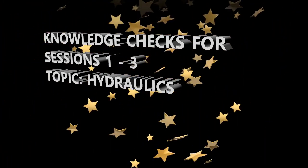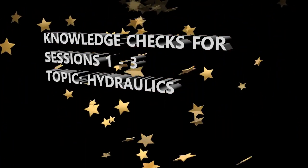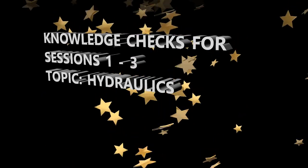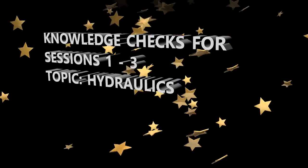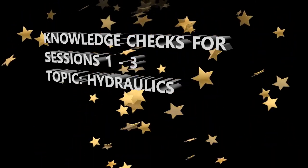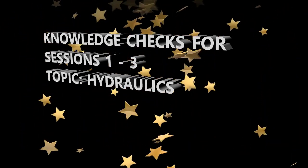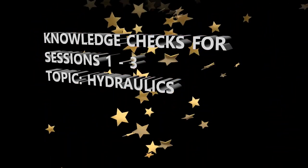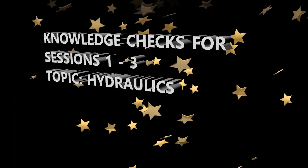Question 14. If the pressure is too low, the priority valve stops the supply of fluid to non-essential users when the pressure decreases to what pressure? Okay, at 1885 psi or 1020 psi? Okay, the answer for that is the first one, the 1885 psi. All right, question 15. Regarding the HP manifolds, how many transmitters are installed on it? Is it 2 or 3? Okay, it's 3.